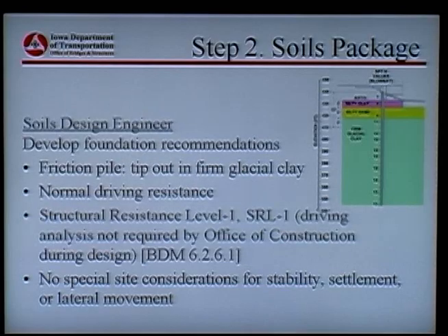Here, the foundation engineer, the soils design engineer, came up with recommending that we tip out in the till, in the glacial clay. Normal driving resistances, SRL1 structural resistance level, so it's 6 KSI, and there's no drivability concerns.